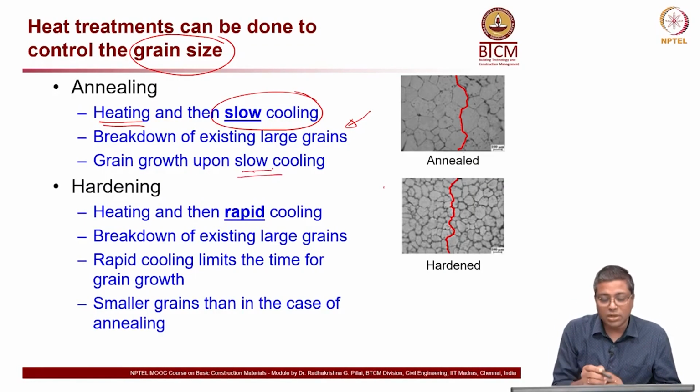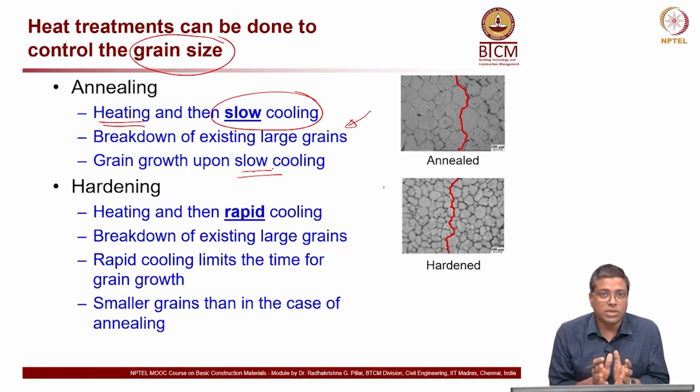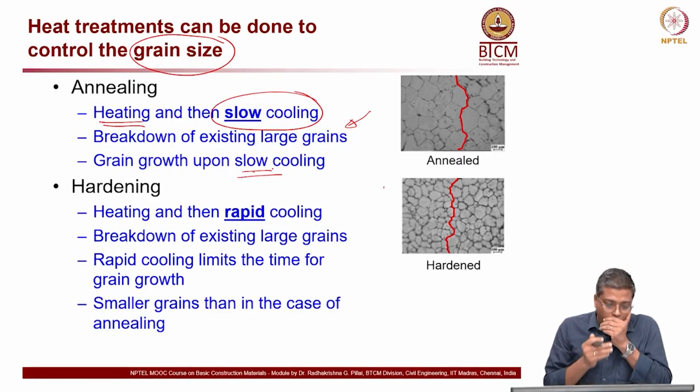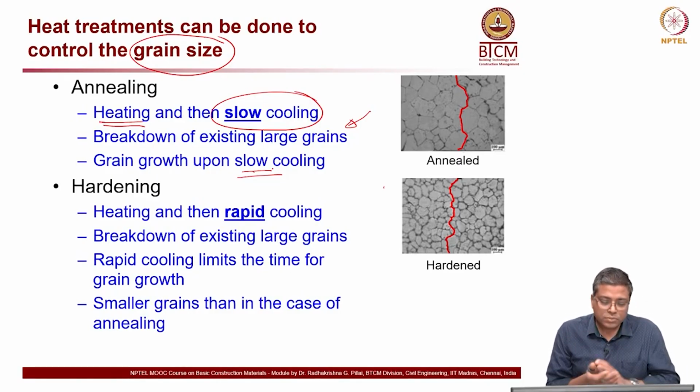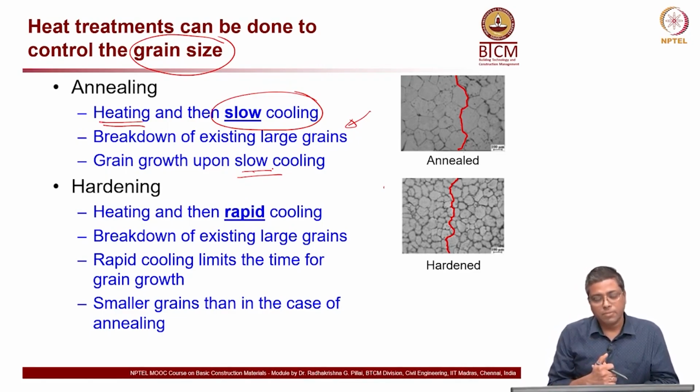That depends on the rate of cooling. So, you are basically rearranging the grains, and this happens not in a molten stage, this happens after the material solidifies. So, you rearrange the grains to a desired level of grain size.